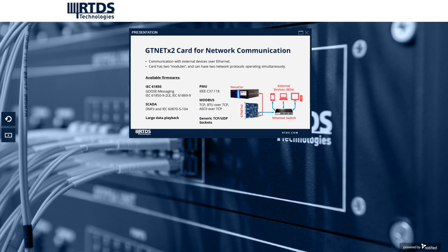We have many users who use the GTNet card for sampled values streaming, and it can both publish and subscribe to sampled values. So each instance of the GTNet SV firmware can publish up to 2 sampled values streams with 24 channels each, or it can subscribe to a single sampled value stream.